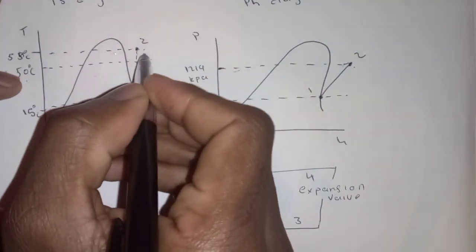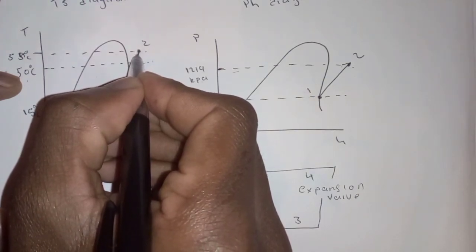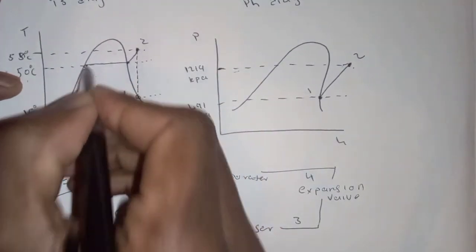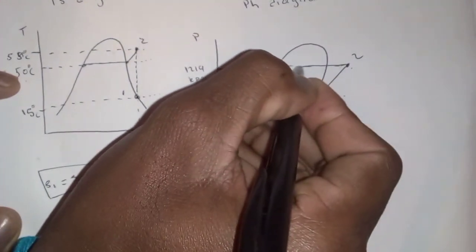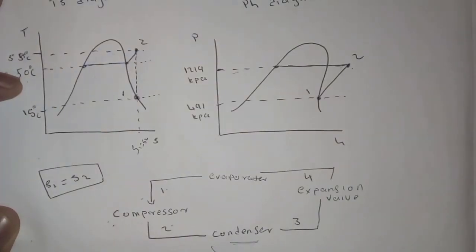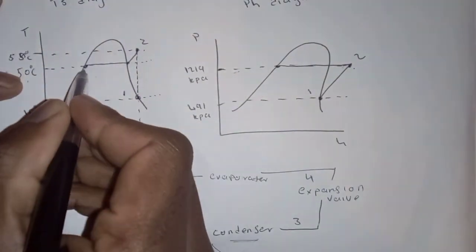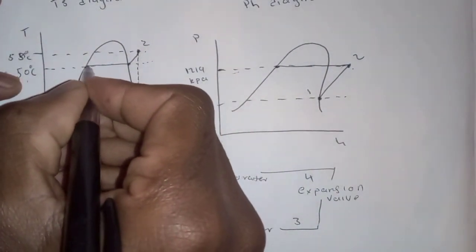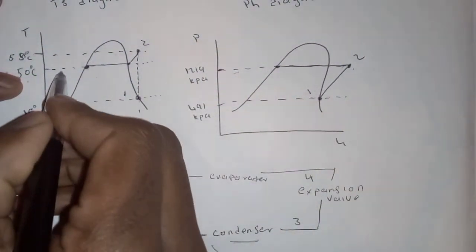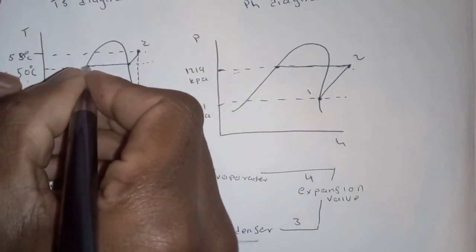The heat energy is being lost. First, it will get from the superheated temperature to the saturation temperature, and then we start the phase change up until we get to this line. Even here, we're going to draw it up until this line. We are told that the refrigerant after the condensation is liquid but not undercooled. So it is within this line because it is not undercooled. If we were told that it is undercooled, it would have been within this region. But since we are told that it's not undercooled, we are going to put it on this line.